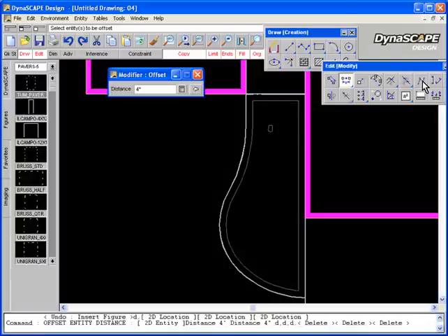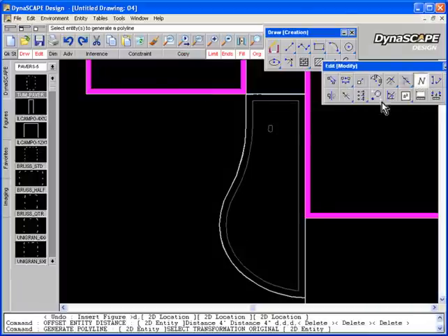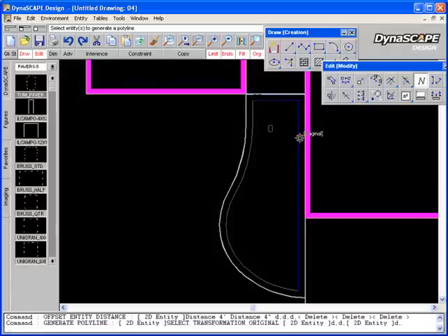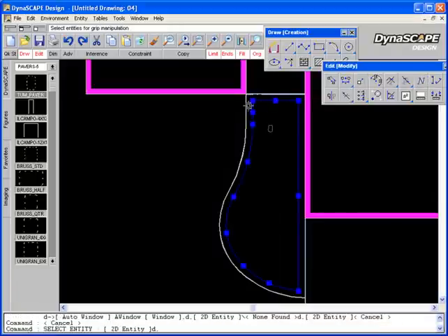And I'm going to use what's called the join tool, which you haven't really seen yet. It will join lines together that are touching end to end. So it'll turn those two lines into one, and turn these two lines also into one. So this now becomes, if I hit escape, a continuous line that goes all the way around the outside. Now when I offset that, that becomes one line, and when I insert the figure along that line with this tool, it'll be all joined together and go in as one.